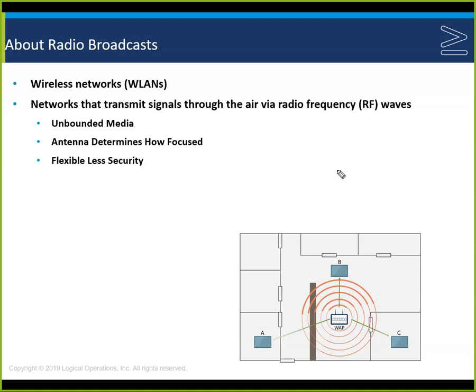We can also have other issues with the antennas and with the wires. If the wire length is wrong, and something comes in here, we can actually shut down our signal. If it's what's called a quarter wave shorted stub, or quarter wave length, in here, that will stop the signal. Different issues are going to happen with all of the wireless and with the signals. The antenna that we use can all affect what goes on in the wire.